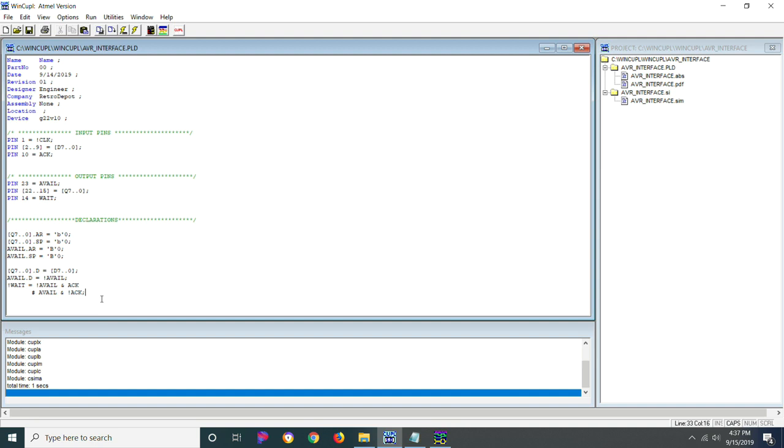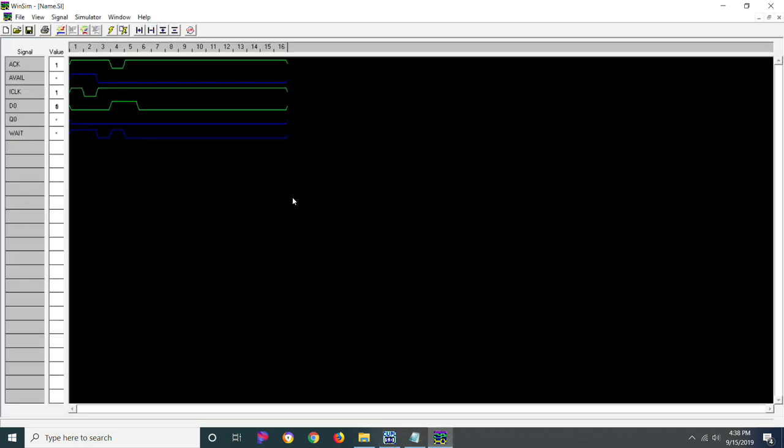And once you have something that works and that you've tested it in WinSim, my advice would be to breadboard it, test it by hand, make sure that everything works the way that you intend it to, and then only then take that information, or take that JEDEC rather, and stick it in a working system.